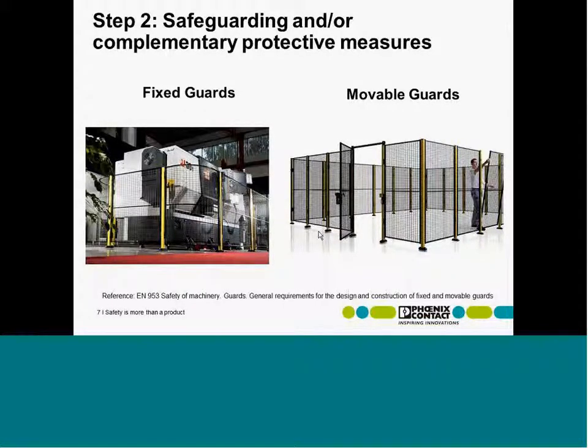In other words, as soon as you open a safety door to enter a hazardous area, you will have an immediate stop of all dangerous machine movements. More technical risk reduction measures, as you will also see in other literature, are light curtains, bumpers, protective mats, and lots of other things, which will be step 2.